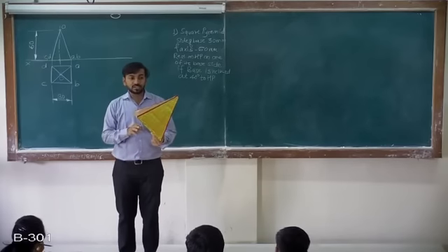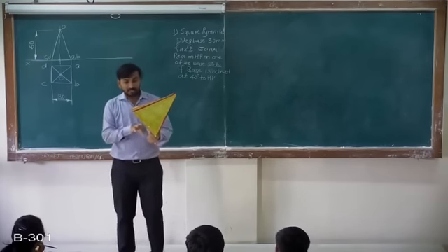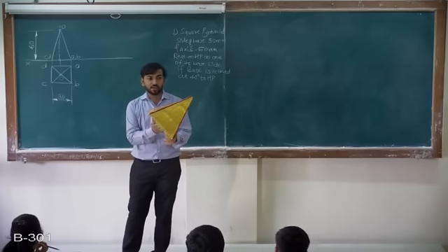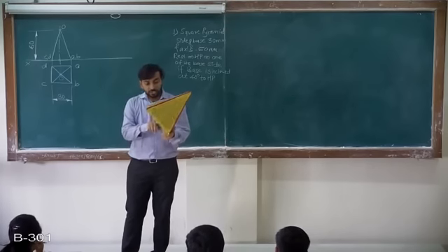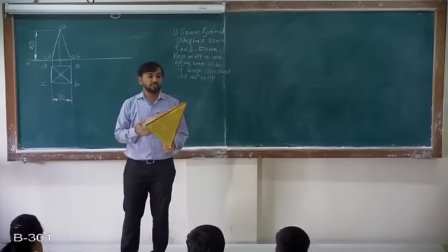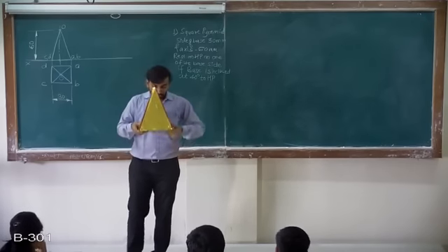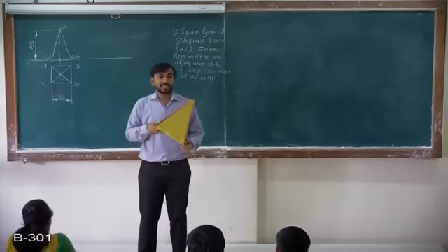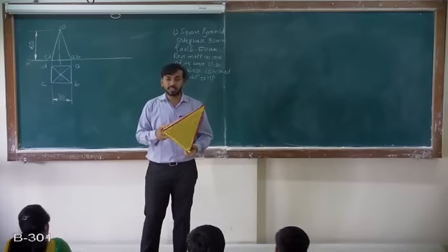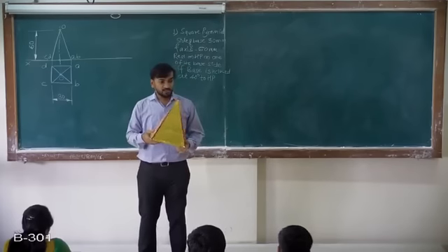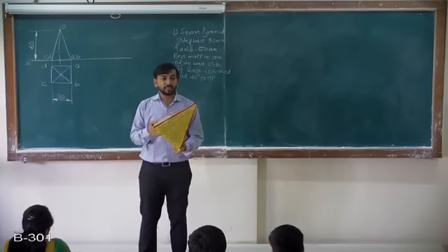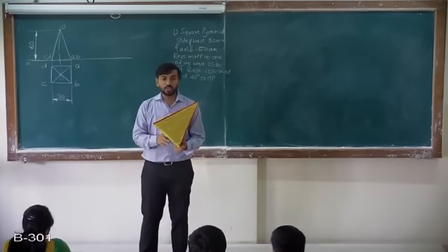So now they have mentioned as second condition, the angle made by this base polygon with HP. How much is it? 40. So this angle given is 40 degree. Always the first stage is resting on HP, and the second is the angle made with HP, or the combination which is related with the HP. So the second condition is the angle made by this base polygon with HP.